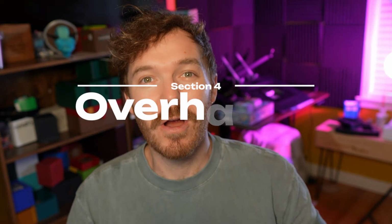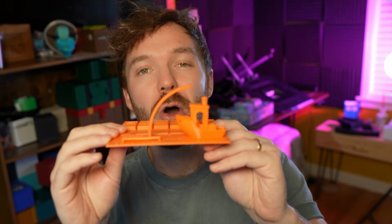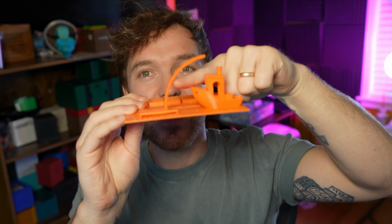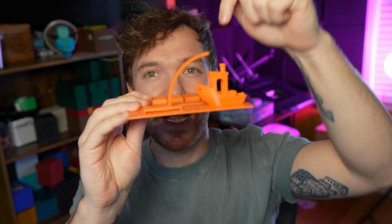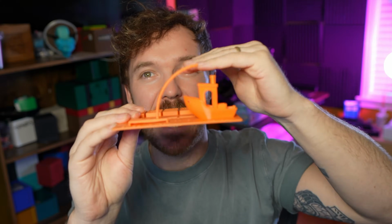Mistake number 4 is overhangs. This right here, and not understanding them correctly. As you get more into 3D printing, you need to learn about having a good print practice workflow where you try and avoid overhangs at all costs. The reason being is as the prints print layer by layer, as it gets more and more angled, it means that the prints are trying to basically print on thin air, which means it can warp, twist, and bend.